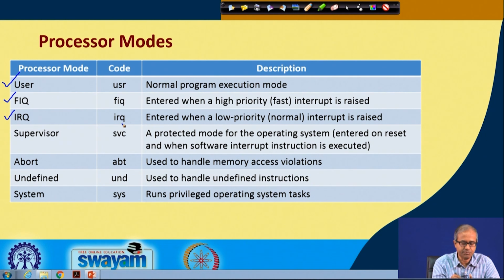This IRQ is the processor mode, you see this FIQ and IRQ we are saying is the mode when the corresponding interrupt handler routine is executing. That interrupt has come, we are handling the interrupt. During that time we say that the processor is in either FIQ mode or in IRQ mode. Okay?